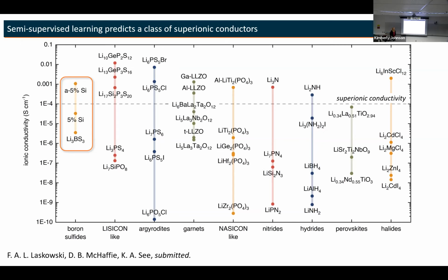For the electrodes, when we make materials, we're doing solid state reactions. You get micron particles, we grind them up, we make electrodes. It's more about how we make the electrodes than how we make the materials. Although with the sulfides, my student Steve spent a long time optimizing these sulfide syntheses. When you make these materials, you seal them in an evacuated tube and heat them up. If you have sulfur around, you're going to have some partial pressure of sulfur vapor in that tube. So you have to have a little bit extra sulfur to satisfy that sulfur vapor pressure. And you have to keep your tubes the same size every time, so they have the same vapor pressure in the tube head space.